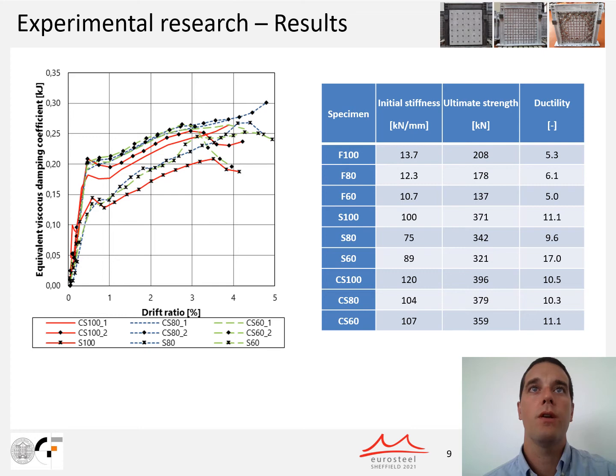This is not in accordance with analytical values when real material properties are used. The above discrepancy of the experimental and analytical results is a consequence of premature failure of the steel infill plate, which prevented complete yielding of the plate in shear.